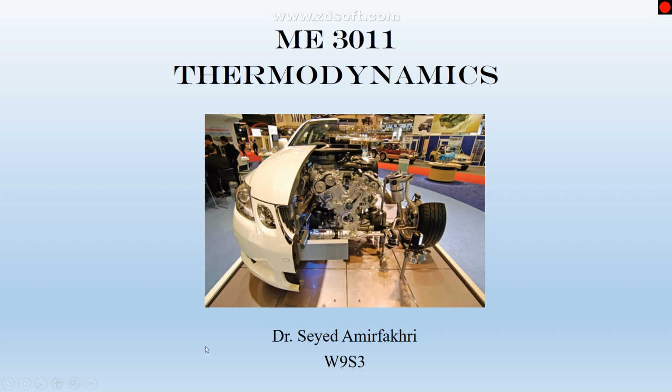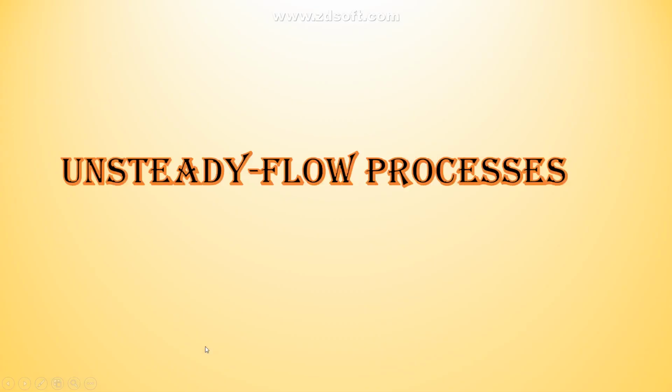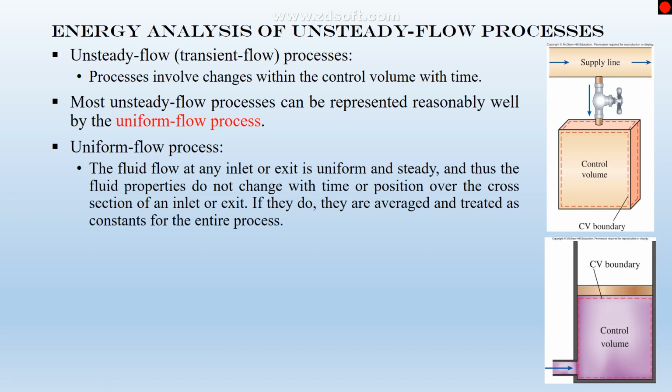For unsteady flow processes, the first thing to keep in mind is that most engineering equipment works under steady state conditions. We already discussed it. You can assume that all turbines, compressors, diffusers, and nozzles work under steady state conditions. So the only case you should be a little bit careful about is a tank during a discharging or charging process.